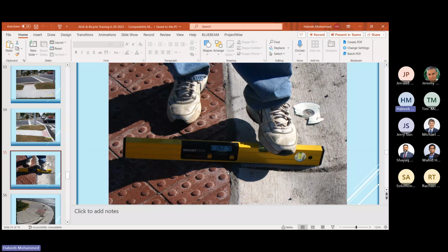And one more thing I mentioned to you guys in my previous presentation, that whenever we are measuring this, the first thing you need to do is calibrate it in the office or somewhere before you even measure anything. And also make sure you have a good amount of battery, because there were instances where you take this inclinometer to the field and there is no battery.